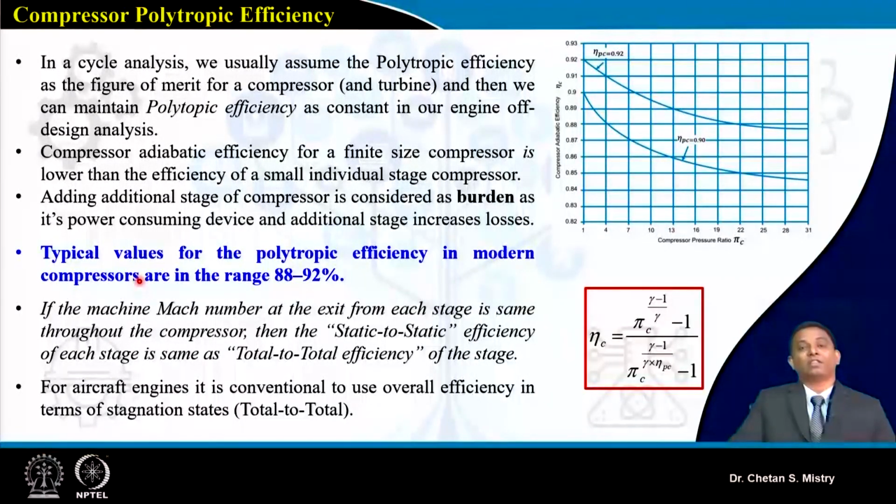Now you say, sir, is this a benefit for a land-based power plant? Yes. For a land-based power plant, we do not have any restriction on the length of the gas turbine engine. You can increase the number of stages. That is what people are doing. They put more stages in land-based power plants so that they are able to achieve higher efficiency and the performance they are looking for.